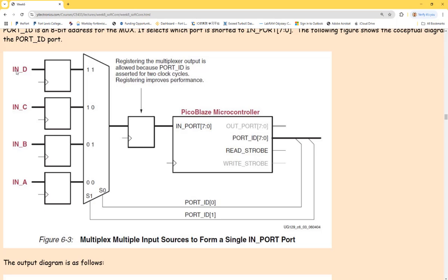Put an ADC over here and directly communicate with your CPU, and you can modify the clock cycles and make it just for that ADC. Make it as fast as you can, without worrying about anything else. It doesn't have to be compatible with anything else on the general-purpose microcontroller. It only has to serve your certain application. So FPGA sometimes can be way faster than microcontrollers, and that is one of the reasons. You can customize every single thing for the system.